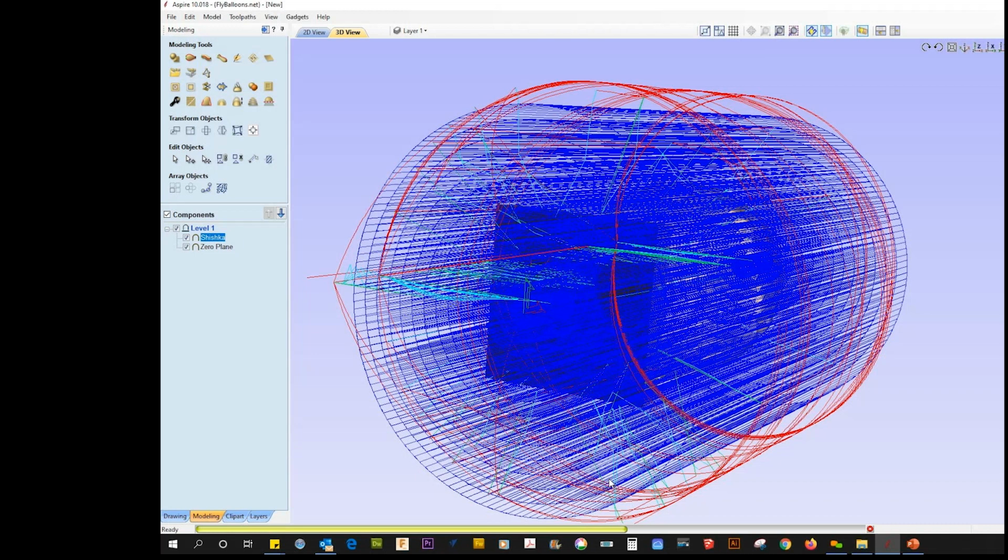I always use a raster, and in most cases, I would run it at 90 degrees, where it's constantly running parallel to your stock piece. By doing that, you can also gain a little bit more speed with that axis. You can move faster.